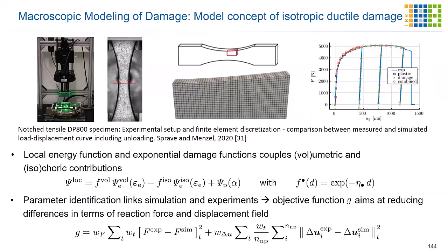As we discussed in another section, due to the degradation and the softening effects, the underlying mathematical problem is not well posed. This all results in mesh dependency of the finite element-based simulations. In order to overcome this problem, different techniques can be used, such as non-local damage models, gradient-enhanced or micromorphic approaches, and rate-dependent formulations for the damage evolution.